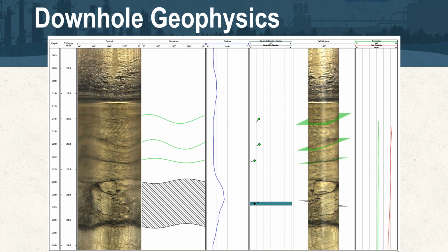But if at the outset, not to be completely concrete here, I can only put in, say, 5 boreholes, I'm probably looking at some of those toolings we talked about, the multi-level port samplers, the liners. I'm probably looking at how we can use those to mitigate the number of boreholes we need to put in, because those can be retracted and replaced, and they do give you various ways to monitor for NAPL or specific zones. But again, they have different costs associated with them.